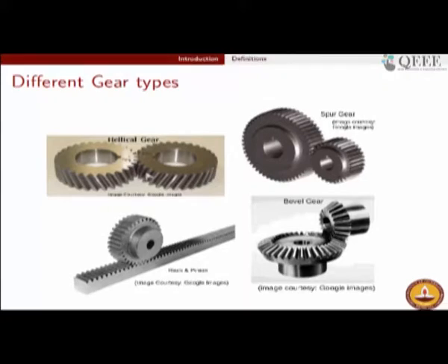Usually helical gears are more costly to make, but it is worth the cost in applications where customers are ready to pay that cost, especially in high end cars where noise and vibration is an irritant. There, most of these gears will be helical gears. But in certain other applications, for example in a lathe machine, possibly in workshop conditions, we are not very worried about additional vibrations, in which case we can tolerate the cheaper spur gear.